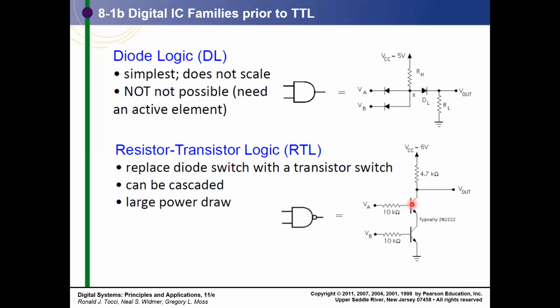Similarly, this can conduct. So there is a current flow in this direction, and these transistors can sink this node, and this node comes to a low value. Now what low value it will come to is one VCE for this and one VCE for this.